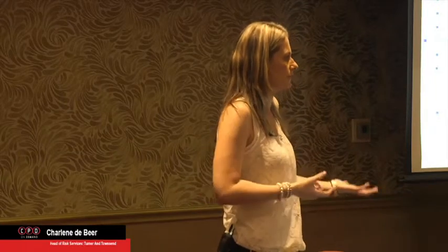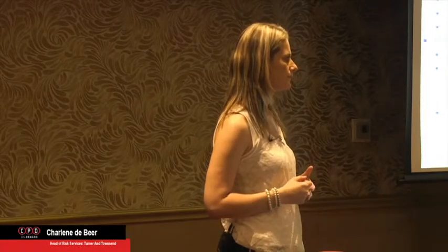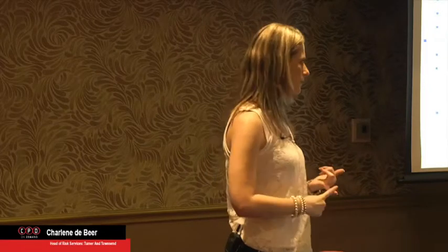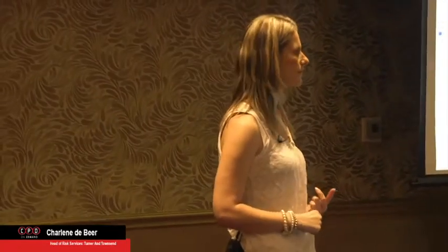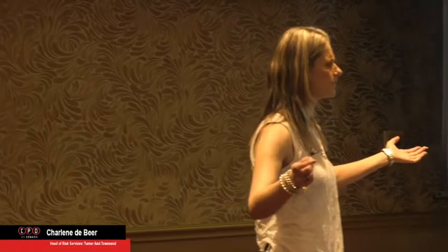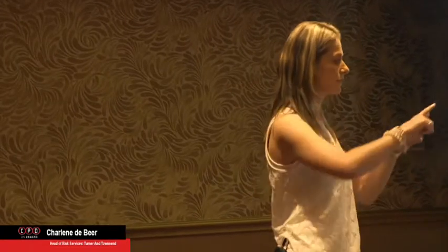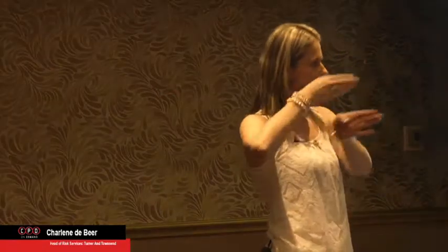By how much, I won't be able to tell you until we do a physical assessment and see how accurate that schedule is. And then you can look at mitigations, like what's the productivity percentage we've assigned to the schedule? 90%. Okay, Mr. Contractor, I've never worked on a site with 90% productivity, so it's inaccurate. Then I'll go back and say, drop it to whatever the trend says, that you've never been more than 60% productive on the site, so you drop your schedule to 60%, because then the date would run automatically, right? Their schedule will slip if they start building in the accurate numbers from their side, and then you do a risk-loaded schedule. Then the overrun won't be attached to the end date, it will just put it where it's supposed to be.